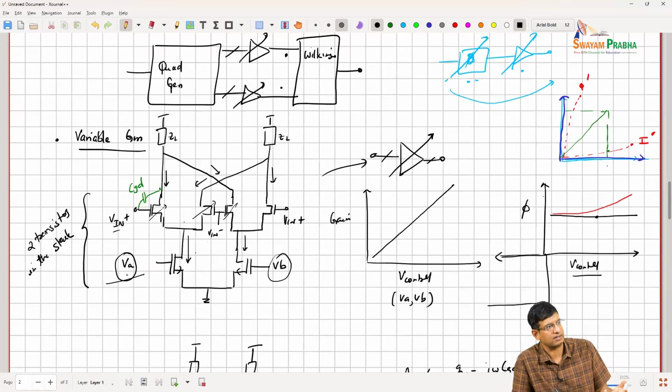That's basically what typically happens. But we do generate the control voltages with higher precision than the phase shifter, because it isn't too expensive to do the control voltage generation with more bits. That's not too much of a problem in CMOS.